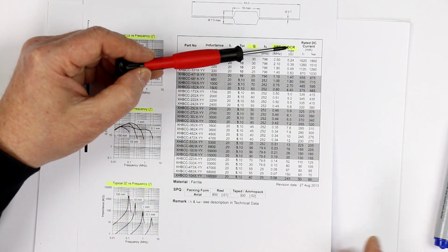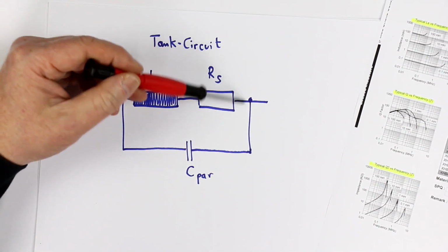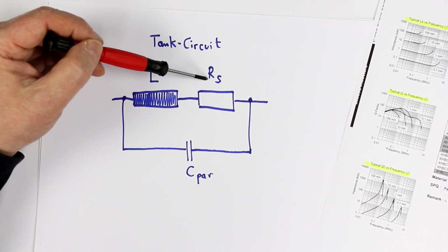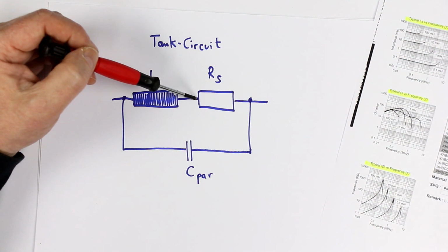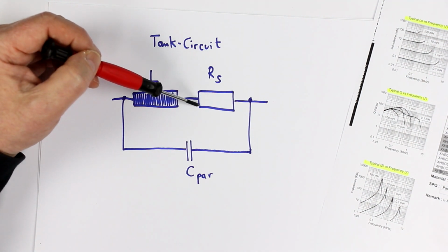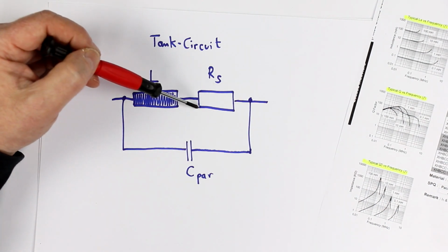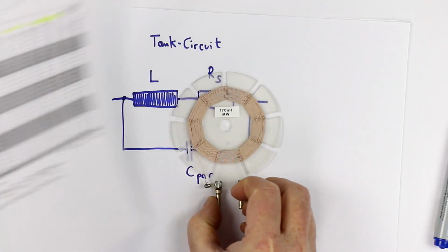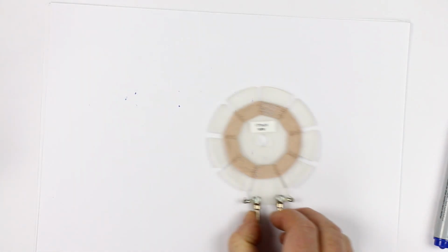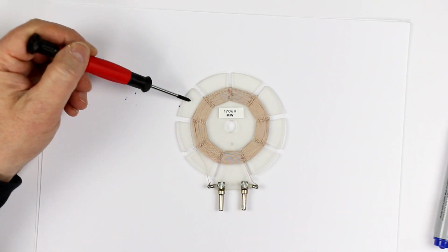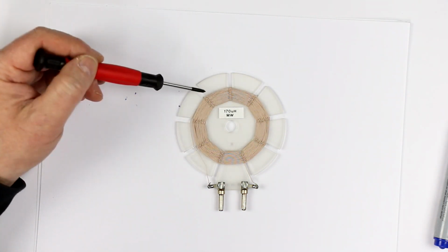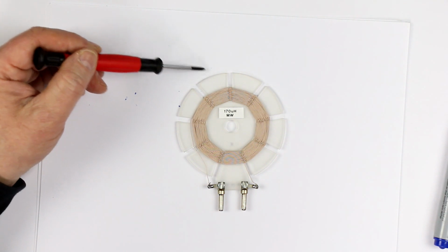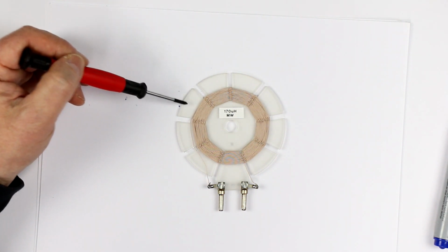And we have the DC resistance, and remember the parasitic resistance here, it's only for DC voltages, it's the copper resistance, but for higher frequencies this resistance rises due to skin effect, proximity effect, and losses in the surrounding material, which most often is ferrite. But if we take a look at another kind of inductor, namely this spiderweb coil, here we don't have any ferrite material, but we have this plastic where the coil is wound on. And here, instead of magnetic losses in ferrite material, you have dielectric losses in the material where the coil is wound on.